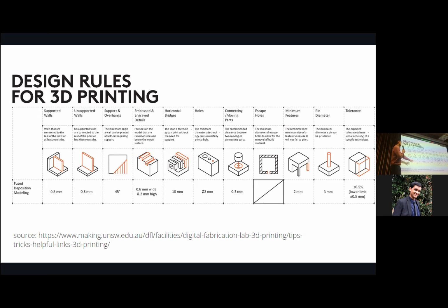So, a support is like a feature, like an overhang is a feature where when you print something, you go up and then you go basically horizontally out. That is very hard to print because on this planet we have this thing called gravity, and when you extrude, right, all the filament basically just drops down. So it's not ideal if you print at a 90-degree overhang, but we can get away with some sort of overhang if it's at an angle.